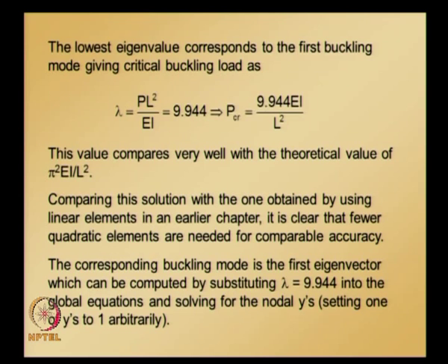We obtained the buckling eigenvalue. The corresponding buckling mode is the first eigenvector, which can be computed by substituting lambda is equal to 9.944 into the global equations and solving for nodal y values.